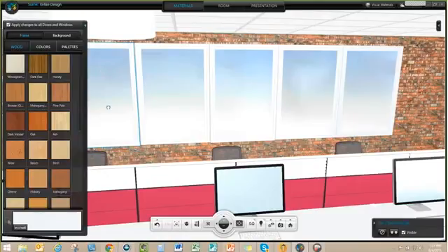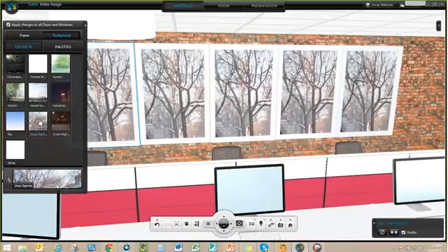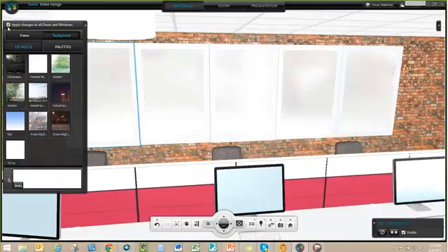First of all, just note that when I pick my window, I can change my material option to look for a background. Couple other things, just like what I did with the wall a second ago, I need to come in and either check or uncheck the apply to all. Because if I have this apply to all and I pick something, it's going to repeat 5 times. Well, that doesn't look very good. So in this case, we'll have to make sure to uncheck this.